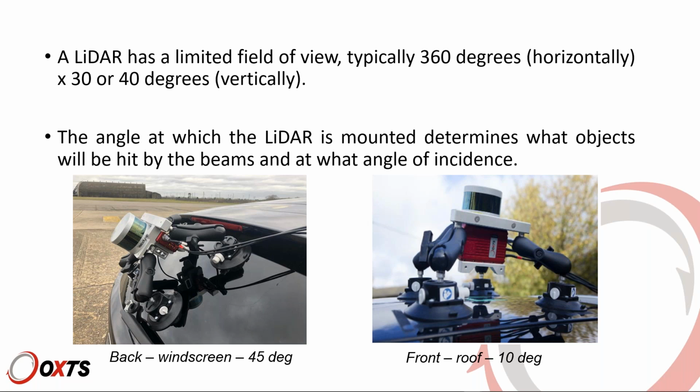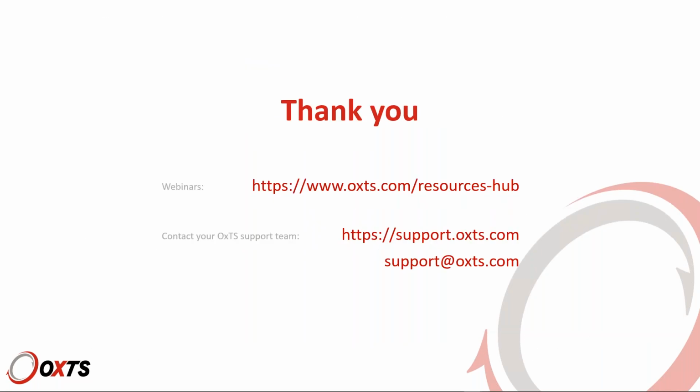Thank you, Sam. Because that LiDAR has a plus minus 15 degrees field of view, that means its field of view relative to the horizontal will be effectively minus 30 to minus 15 degrees. So you're predominantly focused on the road surface with that setup. Also, it will scan the sides of buildings very well as you drive through the area.